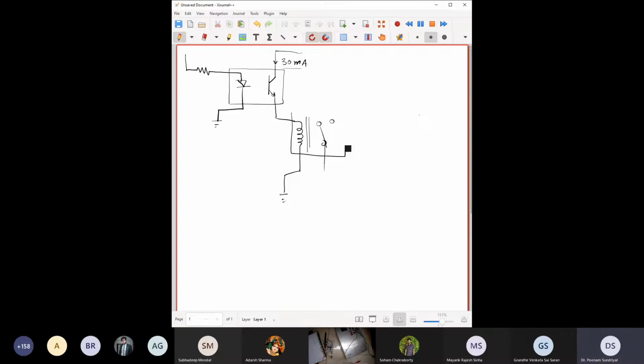Okay, so this is the relay. Even if you use a microcontroller, say 5 volts using an Arduino or whatever, when you're actuating the relay and it switches off, there is no way for the over voltage to go back to the Arduino. Thereby you protect the Arduino and everything else.